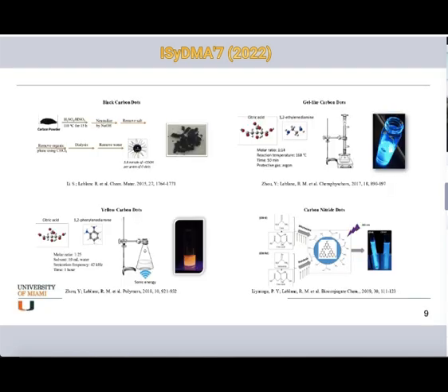Next, I will show you the different types of carbon dust. Again, we have different types depending on the application, and it is very important to mention that. The first one, at the bottom, is the top-down approach. This is the black carbon dust. We start with carbon powder, with particle size around 100 nanometers, and solubilize it in sulfuric acid and nitric acid, then neutralize with NaOH.